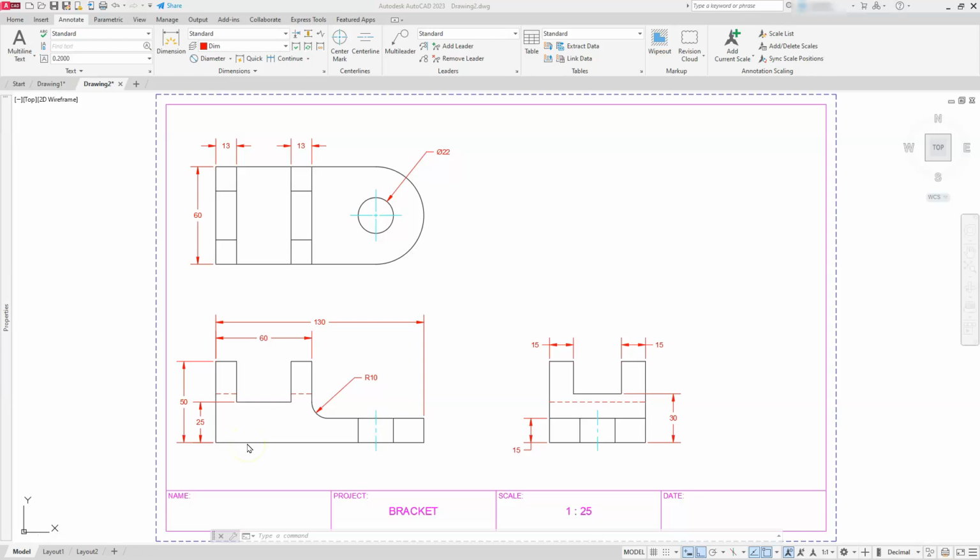The trickiest part that you're going to find when you create isometrics is typically the fillet, and it's mainly because the fillet command does not work. So let's go ahead and start setting up AutoCAD to get it into that isometric profile first. The way we're going to do that is you have an icon here that will automatically set AutoCAD to an iso draft. Once I click this icon, you should see your cursor change.